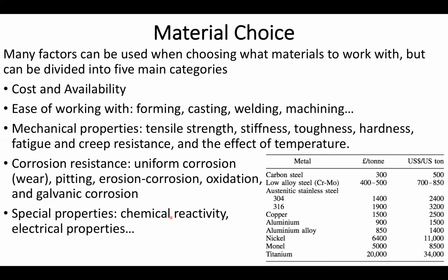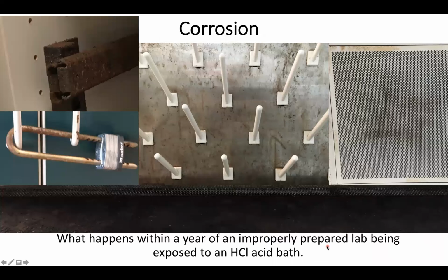So if you're using a lot of amines, you have to watch out about using any metals, because it turns out that you can actually leach away all of the metal from your tubes. So this is a very common driver of corrosion. So again, be very cautious with making sure that the reactivity of your material will match up with the reactivity of whatever chemical you're using. Because again, this can be a big driver of corrosion.